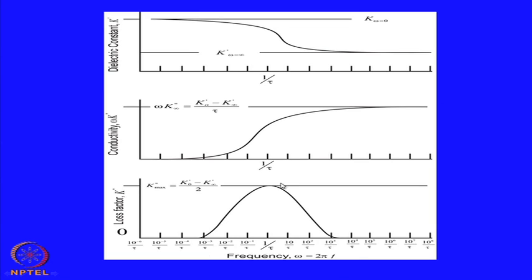Ideally, in a capacitor we would look for a material where the loss is low, because if the loss is high, not only are you losing a lot of energy, but also because of the relatively large current, the whole material will get heated up. So, there will be Joule heating. Therefore, in practice we should look for a dielectric material where the loss is low. That is the normal practice.